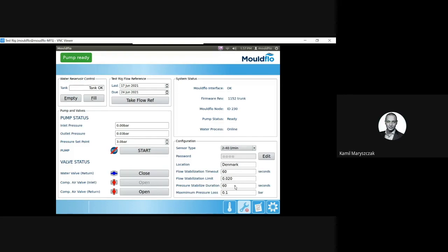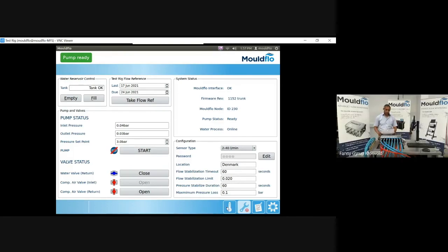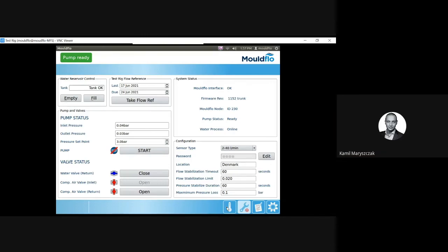Hi guys, this is Camille speaking from Mouldflo UK. Just a quick question, Murali. How do you prepare the test rig for the flow reference test or the flow reference measurement? Yes. So the one thing that we should always keep in mind while doing a flow reference, if I just click on the flow reference, is to open all the ball valves to full on the test rig